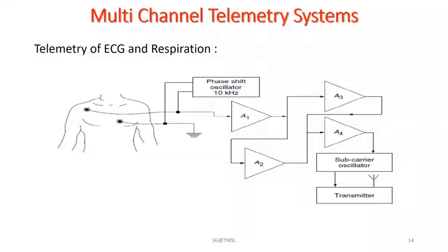Okay, and the FM system, frequency modulation, for similar type of use, may have low power consumption and high baseline stability, but they are more complicated and turn out to be more expensive. They can be troubled by interference between different channels. The techniques for separation usually require expensive and complex filters, and even with these the crosstalk can still be a problem. Since the FM system employs a separate subcarrier frequency for each data channel, it generally involves a high cost.